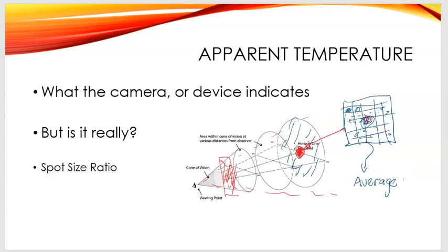And I guess one thing to keep in mind is a lot of times our minds think of infrared because we're used to this laser that's coming across, and the laser does keep that light focused right on there. Sometimes there's even a sight on those handheld infrared temperature sensors. That laser's going to come out and touch that point, but the infrared spectrum that the camera's picking up is still going to be the full field that's in there.